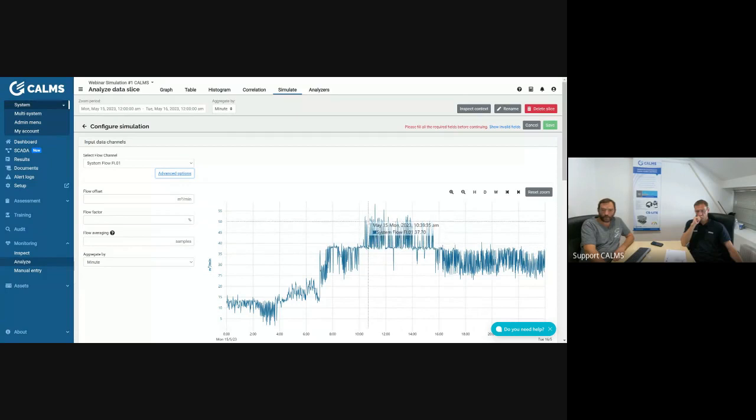Looking closer at the flow profile, we see a lot of very, very high spikes. These high spikes may be because the flow meter is placed very close to the compressors, perhaps even before the storage vessel. And I know for a fact in this case that is what is happening. So trying to simulate these sort of spikes is not going to simulate reality, because in reality, the demand flow is not this spiky. This is the production flow. We can smooth this out in various methods.